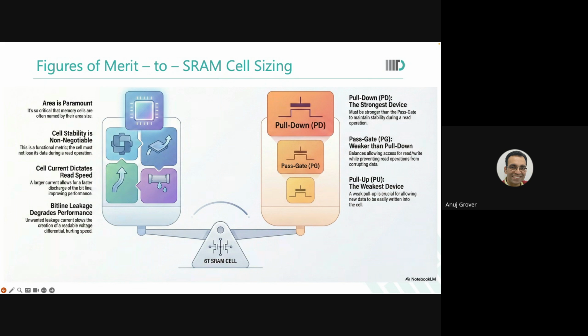Or in many cases, if you look at the memory cell layout, you will see that you can even do DRC violations. You can go beyond the minimum length, minimum width that is prescribed by the technology. Because as you do that, you at once reduce area further. You anyway want it to be weak, so you reduce area further, to gain on both the axes, writability and area. Are you with me? So while there are just 6 transistors in a memory cell, it is fairly complex to design.